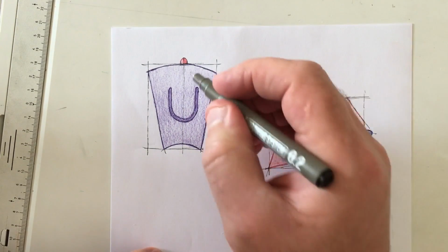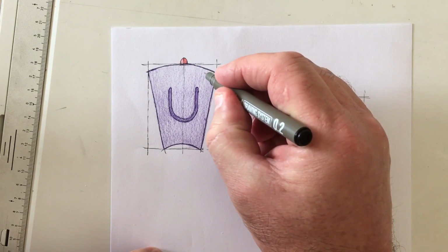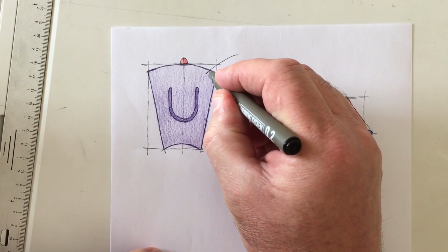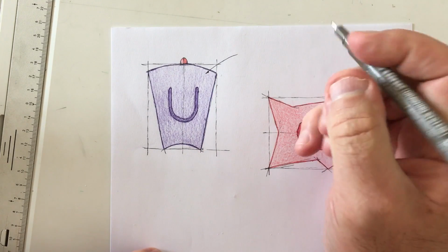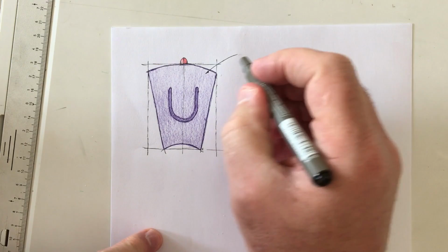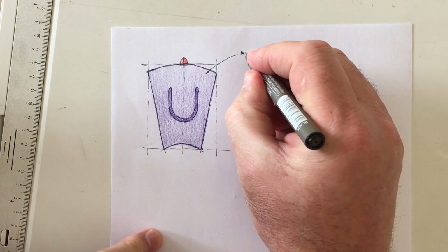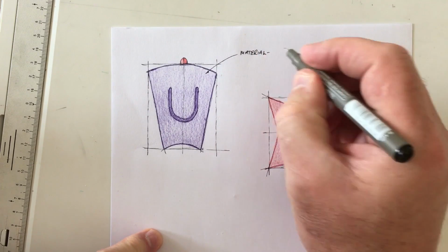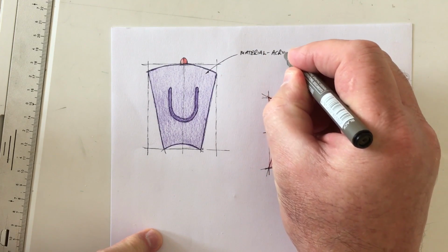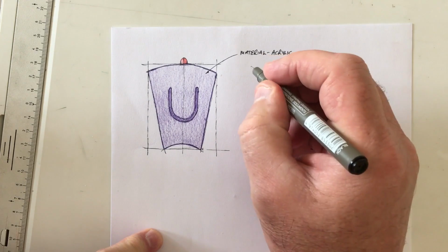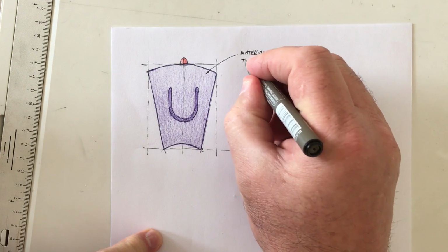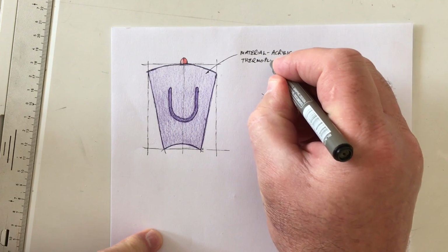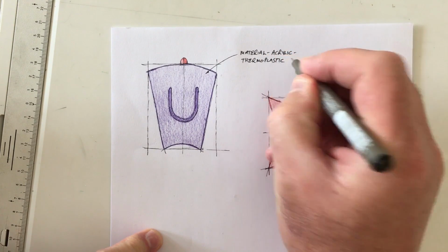So I'm going to start off here and I'm going to put my arrow onto the object, pull away, put a small arrowhead like that, like you've been told to do, and I'm going to write in the word material, and then a little dash. It's acrylic, dash, and I know that acrylic is a thermoplastic. Consider your spelling also, please.